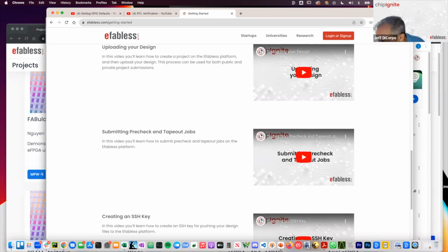Okay, can the chip receive data through the SPI protocol? Yes, there is a master SPI controller as part of the management area. You can find more details on that in the documentation, but you can utilize that for data communication. And there are several examples of open source UART and SPI RTL that you could put in the user project area if you wanted that as an alternative as well. Implement your own as well.